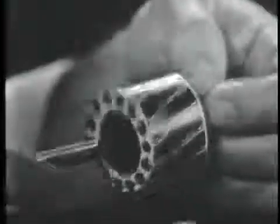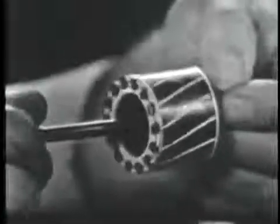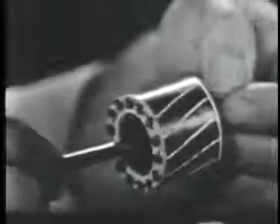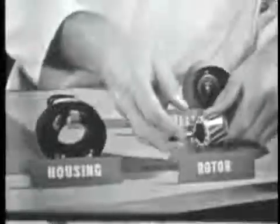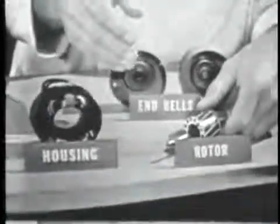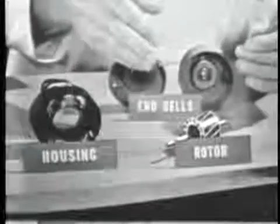Not at all. Now, this particular rotor design is called the squirrel cage rotor because it resembles the exercise cages used for pet squirrels. And like the squirrel cage, the rotor is very simple to construct. Simplicity of construction, which of course leads to lower cost of manufacture, and a very rugged design, makes the induction motor a very popular one. There are no wires on the rotor to burn out, no brushes to wear, no commutator to get scratched or pitted. All in all, a pretty good motor.